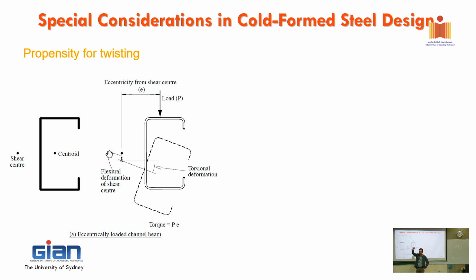In supporting the roofing, or even in the wall systems, or even the columns of the portal frame, they use C-sections a lot. The nature of that section is interesting because the centroid is right here. However, the shear center is in here, a little bit offside.